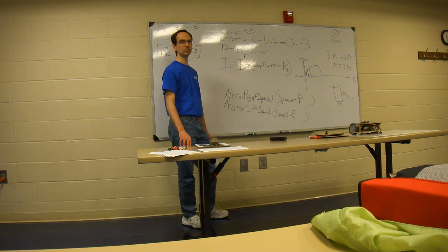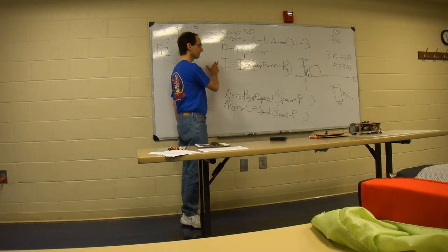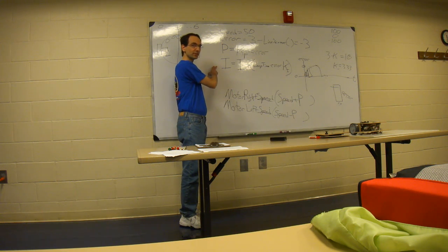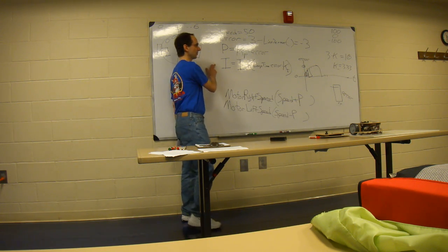You do have to have a differential on the motors, but if you have 0 error, you won't have a differential on the motors. Unless you have an I term, right? I have noticed though that the I term is kind of tricky. It is. It is very tricky. Very hard to tune that one, correct. Yes, it is. I would start out very, very small. Work your way up.